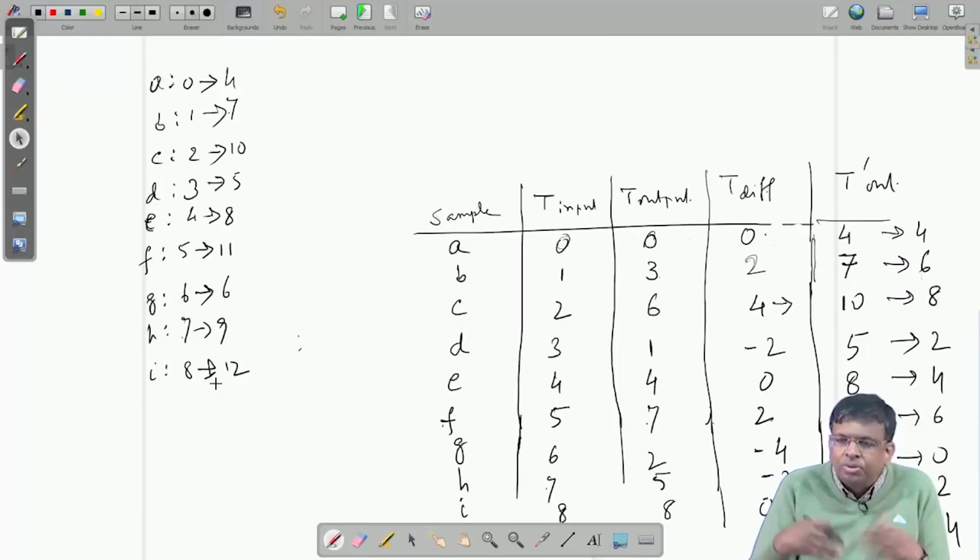So, there will be overlap, as you have seen in the previous examples, and now I have to find out the minimum number of registers required. That is, I have to find out the maximum number of live variables in the system at any clock cycle. I need that many registers. If I have that many registers, then the number of live variables at any cycle will be covered by them, I will be able to store them.